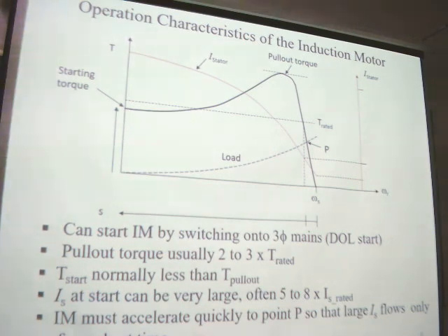We generally want to start a motor more quickly, so we need a larger starting torque. But a larger starting torque will induce a larger starting current. But if the time is short, we can endure it.